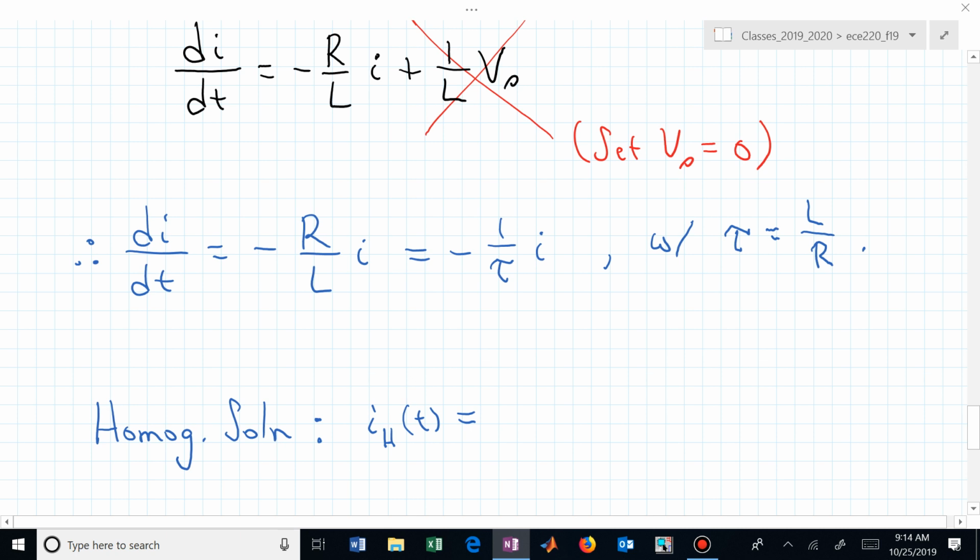An exponential. And in this case, since we have passive circuits and our resistors we're assuming right now, we don't have any dependent sources, we're assuming our resistors are positive, we now have a dissipative system, so that exponential is actually going to be negative. The structure then of this homogeneous solution is now A e to the minus t over tau.